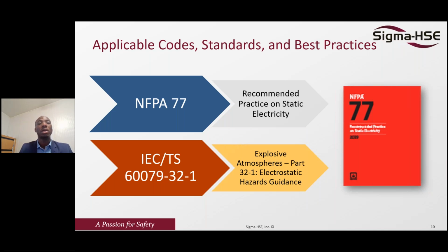So these are the various applicable standards that we normally use. In the United States, we have the NFPA 77, the recommended practice for static electricity. So the 77 is always used. In Europe, we use the IEC TS 60079-32-1. So that is the one used in the European standard.